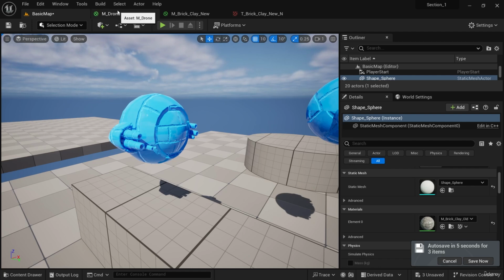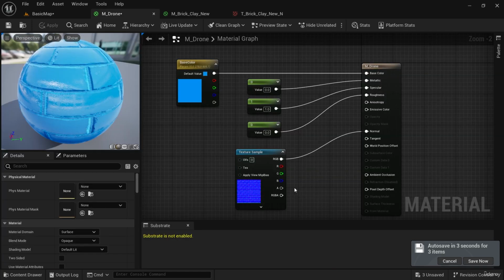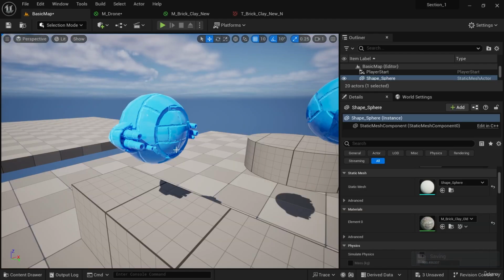That Unreal Engine material asset has to be constructed with nodes here in the engine from the textures that were generated for that asset. So in a realistic game development setting, this will often be the case where you're given an FBX for the mesh and a set of textures for the material. And you have to have a basic understanding of Unreal Engine materials so that you can construct that material asset and apply it. That's what we're going to do now.